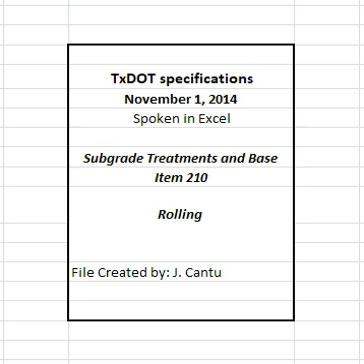2.1 Static steel wheel rollers. Furnish single, double, or triple steel wheel, self-propelled power rollers weighing at least 10 tons capable of operating in a forward and backward motion. Ensure all wheels are flat. The contractor may use vibratory rollers in the static mode when static steel wheel rollers are required. For single steel wheel rollers, pneumatic rear wheels are allowed for embankment, subgrade, and base. Provide rear wheels for triple steel wheel rollers with a minimum diameter of 48 inches, a minimum width of 20 inches, and a minimum compression of 325 pounds per inch of wheel width.